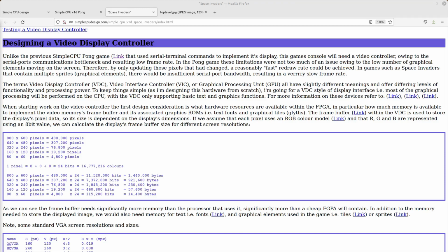You can buy FPGA boards that have external memory, typically a DRAM attached to them. But again, that adds cost to the FPGA board, and also you need to use up some of your FPGA's resources to build an SDRAM controller to allow the processor to interface to this external memory. A far simpler solution is to use the FPGA's on-chip memory to make a system-on-a-chip design, to have a single IC-based solution. And that's what I wanted to go for with this games console.